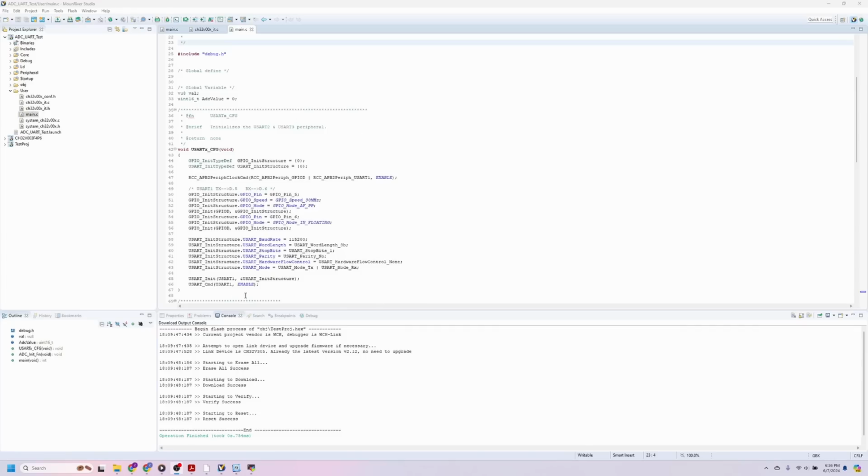On to the more complicated example, reading a voltage with the ADC and sending it over serial to a computer. Setting up the UART here couldn't have been easier, literally, because it's already done for you in the start code. There is a debug file included. You can go through and check out the exact functionality, but one thing it does is redirect printf to UART1. All you need to do is know the pins, PD5 for TX and PD6 for RX, hook them up to the Link-E appropriately, and then printf just works.